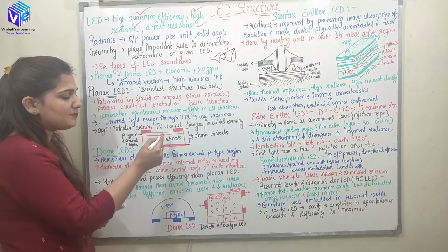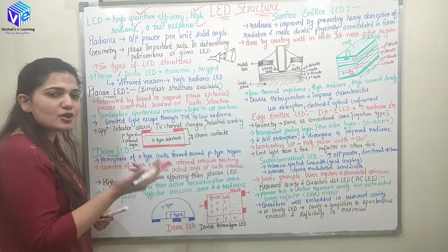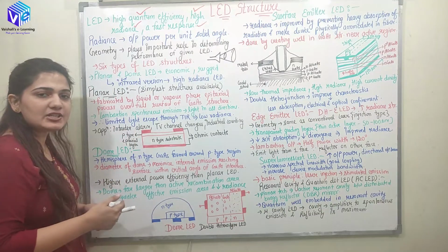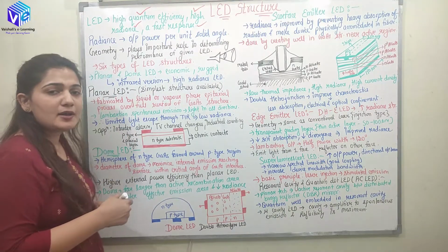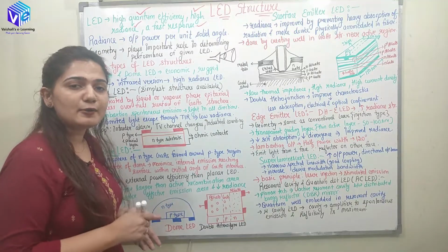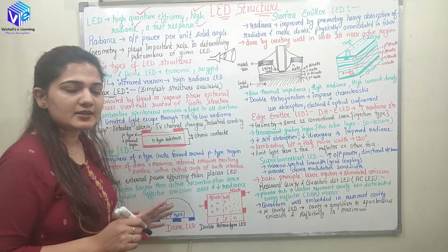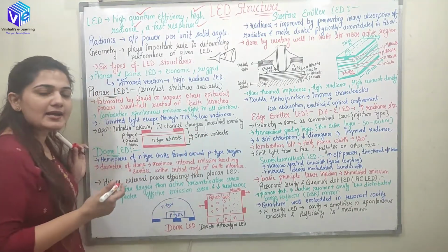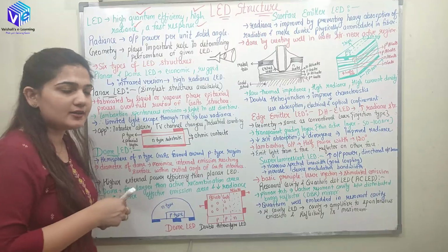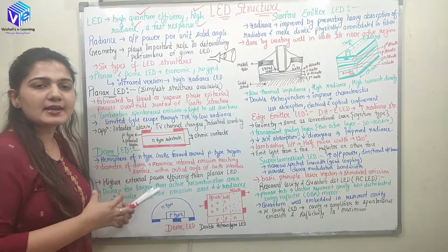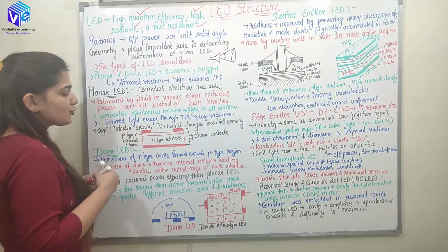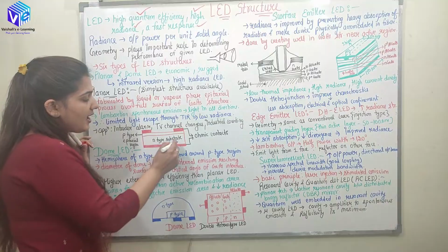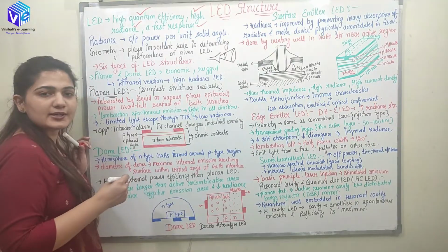So I have N type doped substrate, could be silicon or germanium or the gallium arsenide substrate. Over that we have the P-type epitaxial layer which can be developed or deposited here with the help of liquid or vapor phase epitaxy. Here I will be making the ohmic contacts so that I can get the input current inside this structure and I can measure the output current as well. So I have to make the ohmic contacts over the P-type epitaxial layer as well as below the N-type substrate.